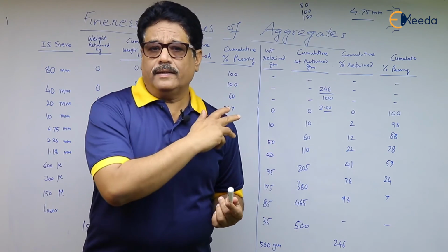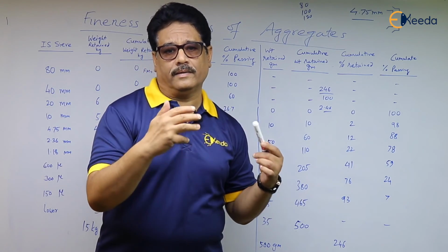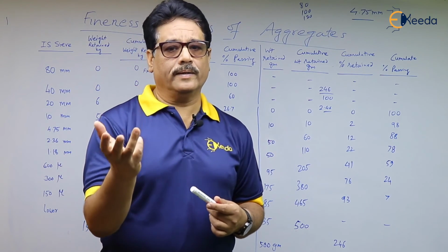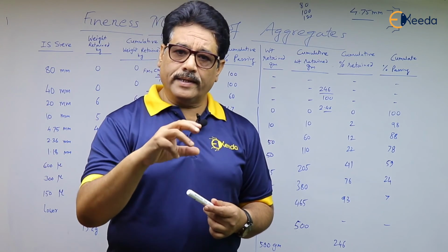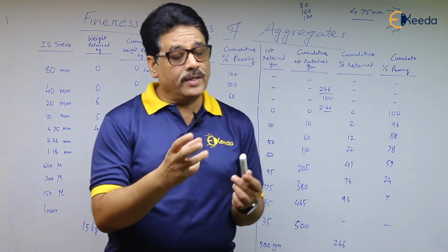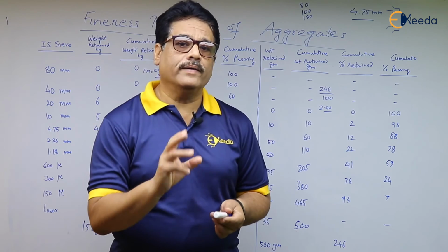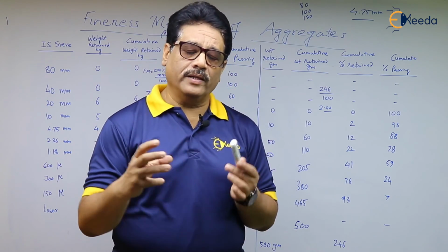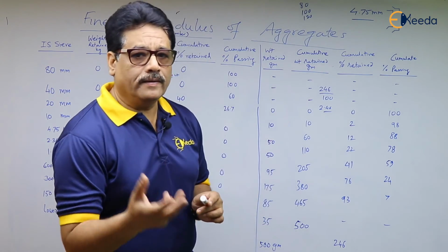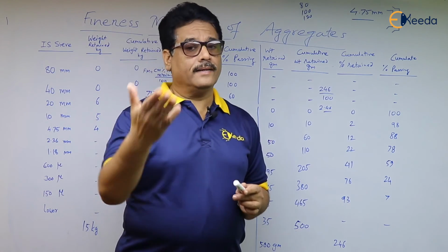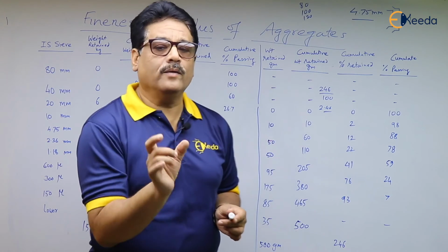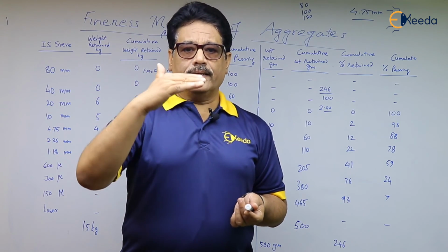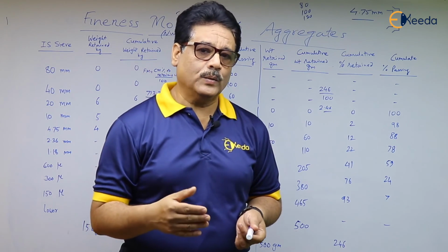And we have seen in another article the effects of aggregate properties on concrete making. If the coarser aggregates are more, they may be helpful for workability, but there may be some problems again of filling up the gaps. So IS code has given the grading of aggregates, which we have also seen, and the grading curves are also available in the IS codes.